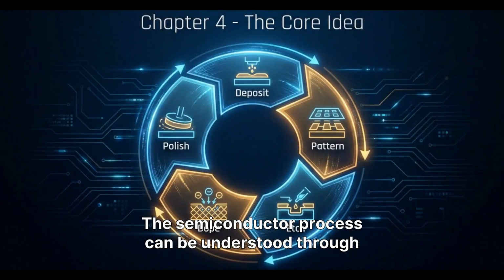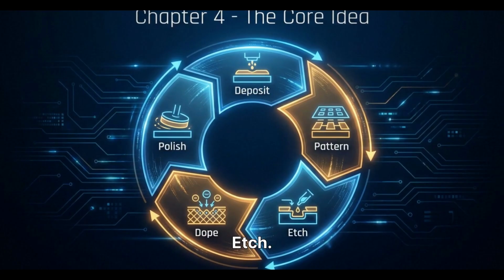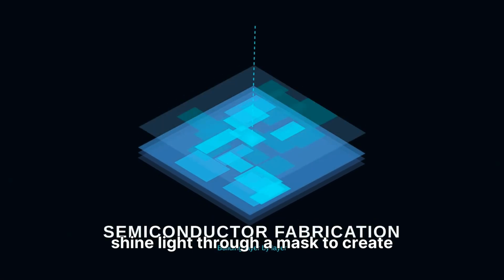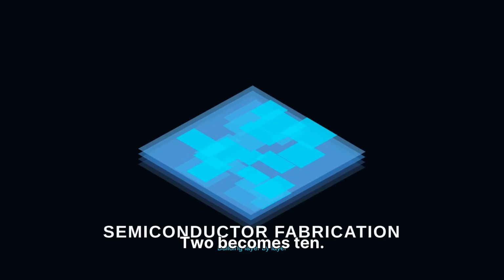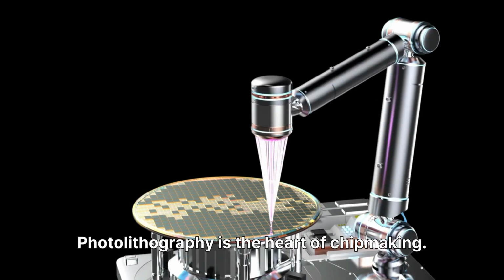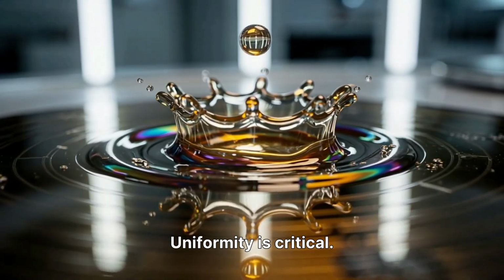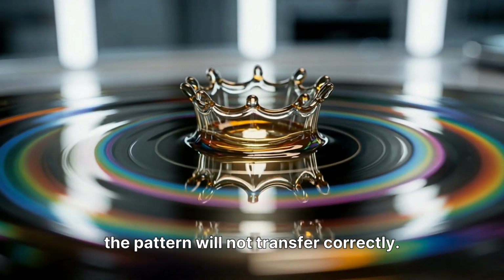The semiconductor process can be understood through one simple cycle: deposit, pattern, etch, dope, polish, inspect, repeat. Using a light-sensitive chemical called photoresist, engineers shine light through a mask to create a stencil. One layer becomes 2, 2 becomes 10, 10 becomes 50. Photolithography is the heart of chip making. It means writing patterns on a surface using light. A liquid photoresist is spread on the spinning wafer. Uniformity is critical. If it's too thick in one area, the pattern will not transfer correctly.